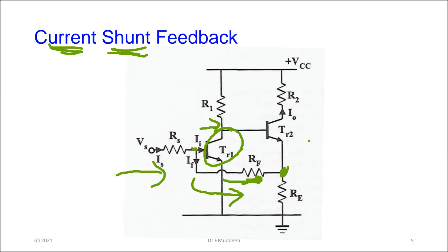All right, but the important thing is that from what you did before in your first year electronics and some of what you did here, you know how to design amplifiers, you know how to bias the amplifiers, you know how to get from the specs, so you could choose the various components in there. And now with the discussion on feedback and what we're going to do a little bit later on, you will be in a position to see, okay, if I want to make a constant feedback amplifier, how to size RF and so on. And you could read the handout that I gave you, which has the information on how to go about and figure out a design if you want to.